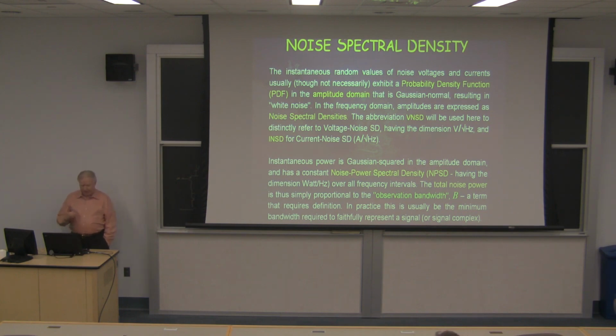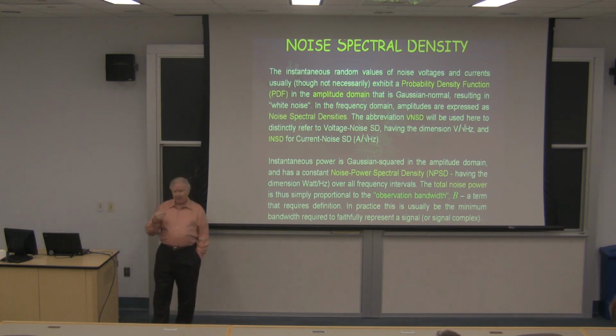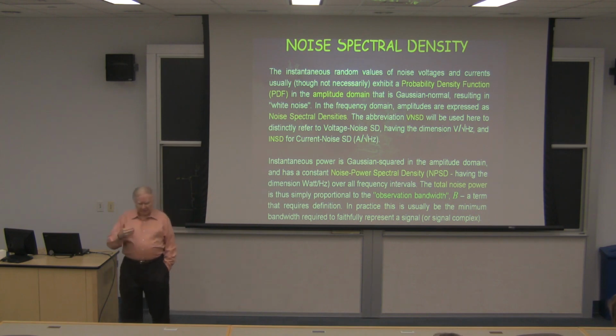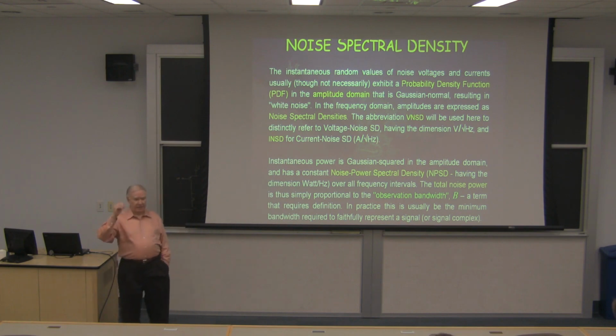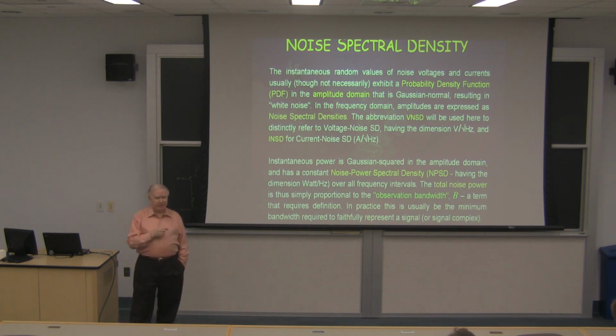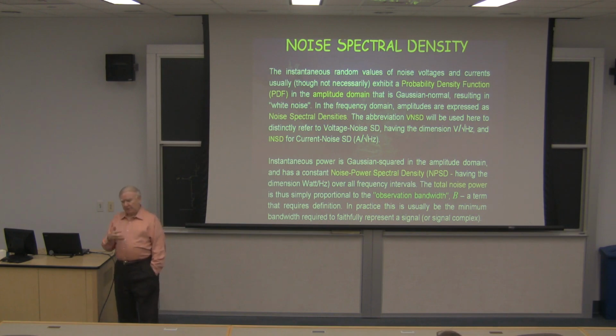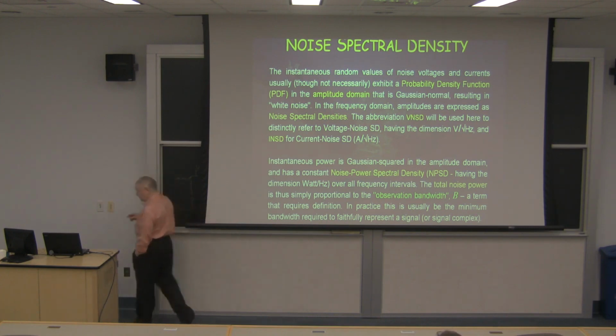Now, power, of course, is a more important parameter in such applications as radar receivers and cell phone receivers, because always you're fighting the available signal power, or the available signal power is fighting against the thermal noise floor and other thermal noise mechanisms in the front end of the receiver. So it's usually more important to talk about noise in power terms than in either voltage or current. I mean, you can imagine, just to take a silly example, if you had an electrostatic generator of 100,000 volts that had a fluctuation of a volt on it, so what? It doesn't amount to anything in terms of power, even though it's a very large voltage variation.